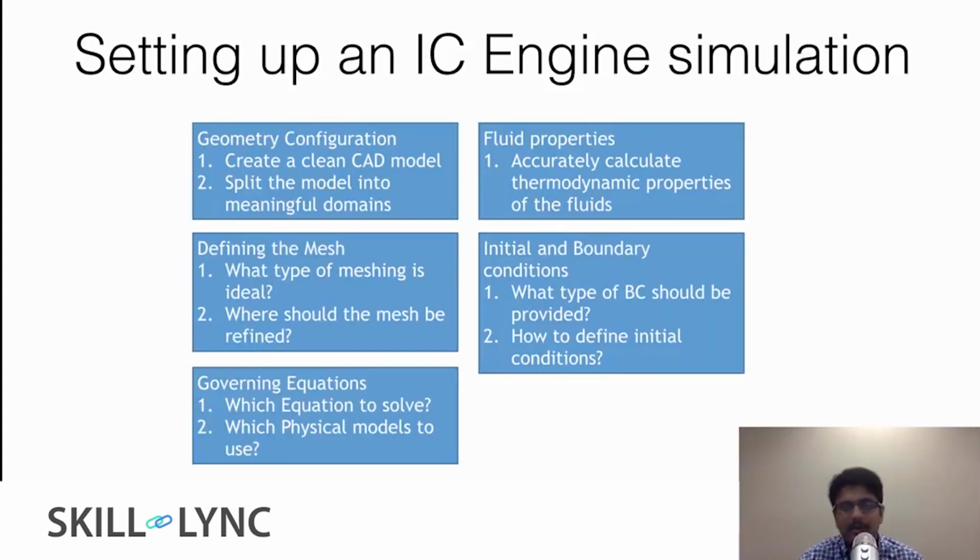So we start with geometry configuration. Here we create a clean CAD model and we split the model into meaningful domains. And then we need to calculate the fluid properties accurately. We need to define the mesh.